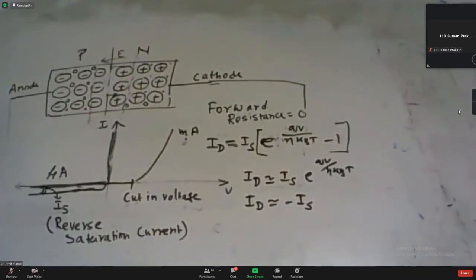That means the circuit must consist of linear components, but a diode is a non-linear component. So in any circuit, if we need to apply KCL, KVL, Thevenin's, Norton's or the superposition theorem, then obviously the element must be linear.